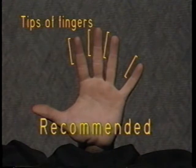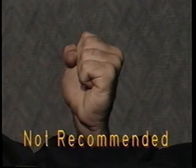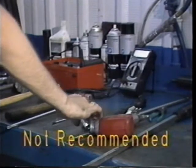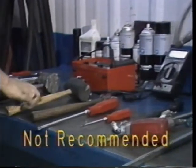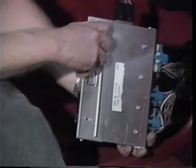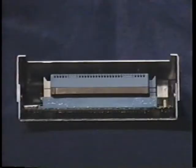The ECM should be tapped using only the fingertips of one hand. Use of the palm, fist, or any type of tool subjects the ECM to excessive stress. The force generated can cause both the circuit board and the outer aluminum case to flex and distort beyond design limits. Tap only on the top, the side with the MEM CAL door. This will minimize the chance of deflecting the ECM case into the electrical leads on the circuit board. Also, tapping close to the edge of the ECM, especially near the corners, is best.